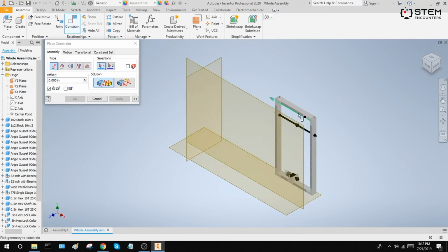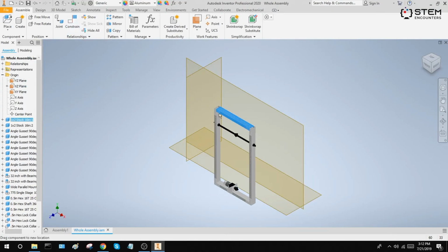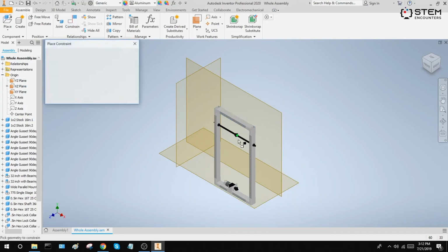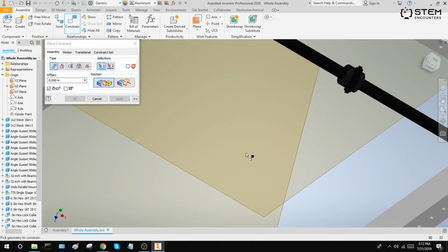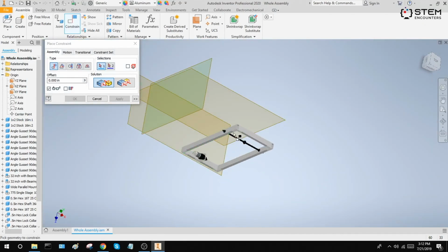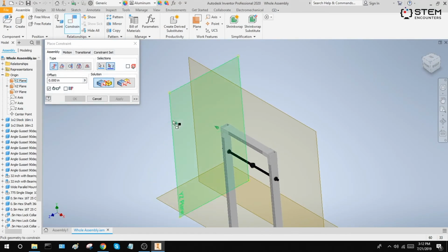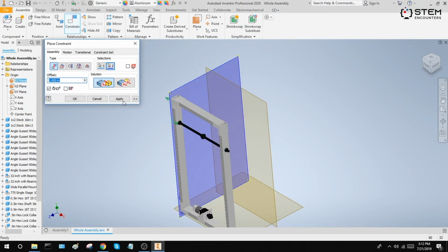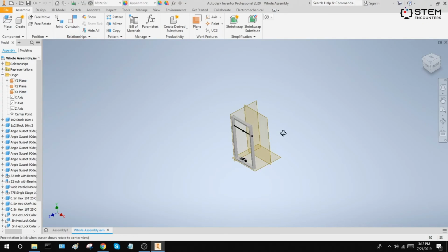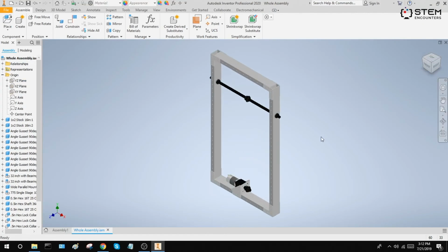Now click apply, and if necessary, we can add some more constraints, though currently it's not really necessary. But say if your assembly was angled for some reason, you'd also want to make another constraint to another plane. Now after all that's done, go ahead and hide the planes and click the home button, and your assembly should be oriented correctly after you're homing your view.